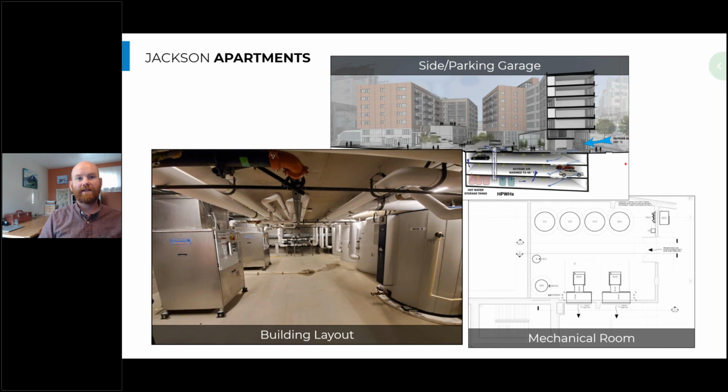If we were to put these on the roof, there would be significant portions of the year where it's cooler than 40 degrees Fahrenheit outside, and so those heat pumps would not be heat pumping. They wouldn't be moving that heat into the water because it would be lower than the minimum operational temperature. So that warmed air that's now 40 degrees on our design day gets drawn in to our mechanical room on one of the lower levels of the parking garage.